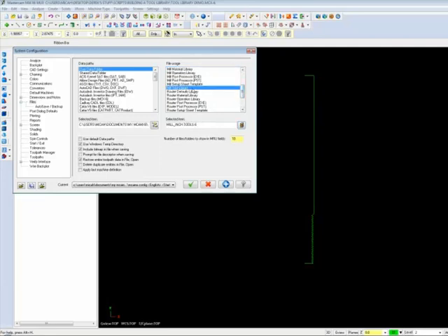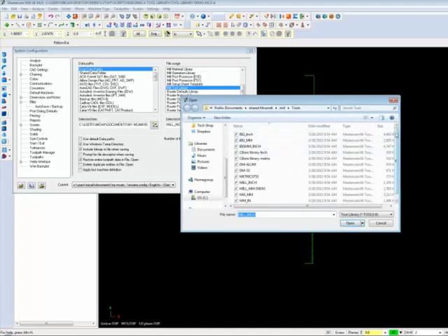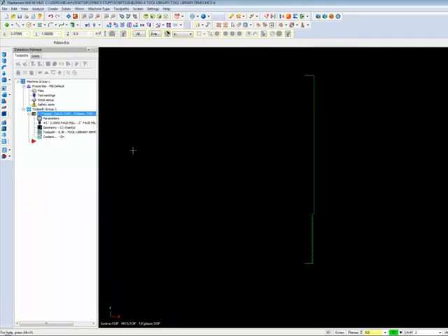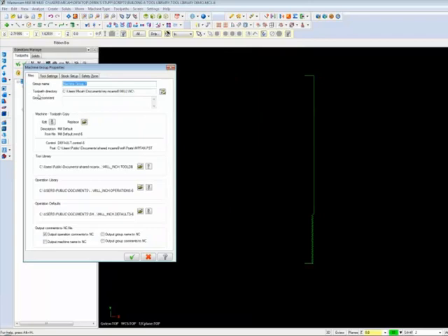Under that, you see mill tool library. In this case, it's looking for those tools. So you would set that tool library on the network, on the server that everybody can share, so that they automatically default to that. You can also do the same thing for machine configuration. Mike, do you remember if it's under the control or under the machine definition where you set what tool library? It's in the machine definition under the general machine parameters. You can select your specific tool library and or material library there, and it will only be loaded when you load that particular machine definition.